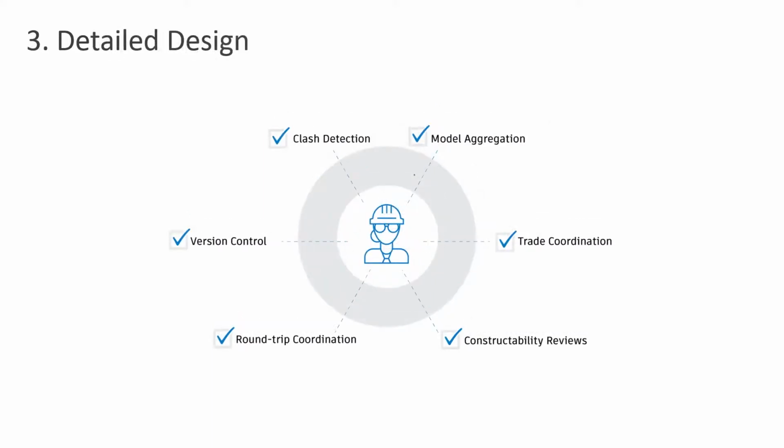And then looking at maybe your detailed design stage, what about when you've moved your design model along and you want to run some clash detection as well? Rather than just running it on your own machine, in an isolated process, you're able to run that in BIM360 as well, and then you're able to raise issues where any of those may have come up, particularly around clash detection and coordination issues. And you can assign those particular issues to different responsible people as well.